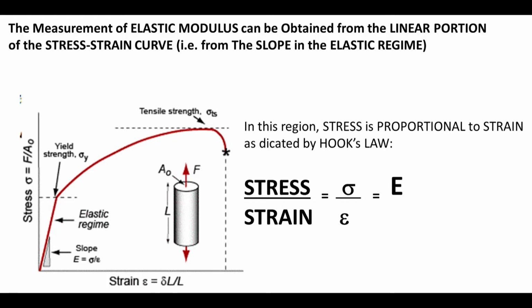And therefore, strain becomes a very difficult parameter to measure accurately and hence creates a large error in the slope of the elastic region and therefore large differences in the measured modulus of the materials.